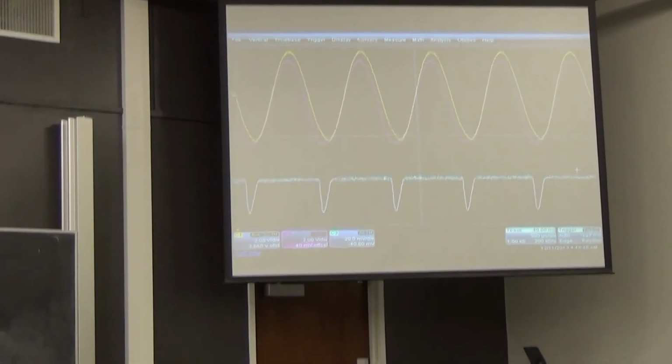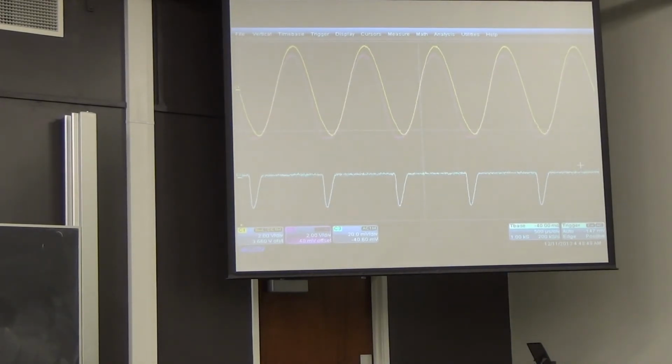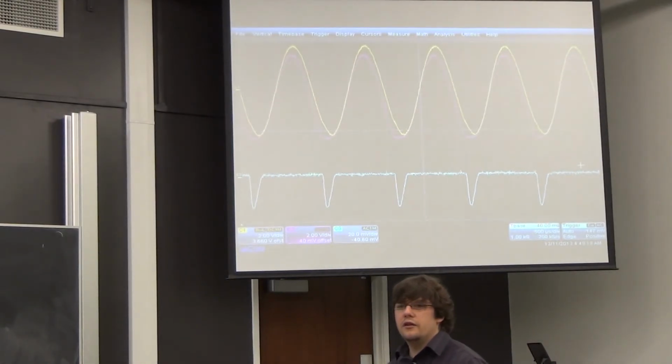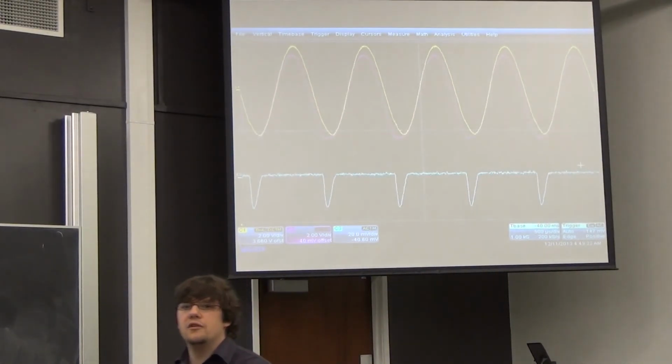So, yeah, just pull that out. If you look at the yellow waveform, you must be quite careful when you read the oscilloscope like this. The yellow waveform reference, that's to say 0 volts for the yellow waveform, is where the little marker is on the left that says C1, which is about 3/4 of the way up the screen. And the yellow waveform is symmetrical about the marker. That's to say, it spends half of its life above the marker and half of its life below the marker. So this is regular AC with no DC offset, or no appreciable DC offset, not more than a few millivolts.